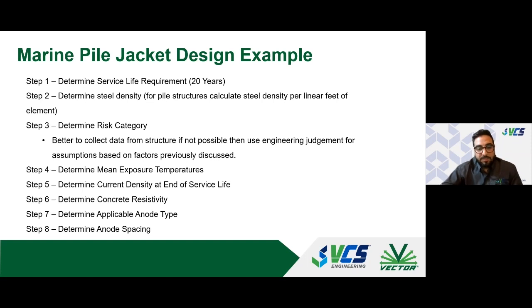Going into the marine pile jacket example, I've outlined some of the steps that I typically conduct during my design practices. Step one is really to understand what service life requirement I'm dealing with. How much am I trying to extend the service life of the structure by? And these are very important questions that we could ask the owners or the engineers that we're working for at the beginning of the project to be able to provide a viable and appropriate solution.